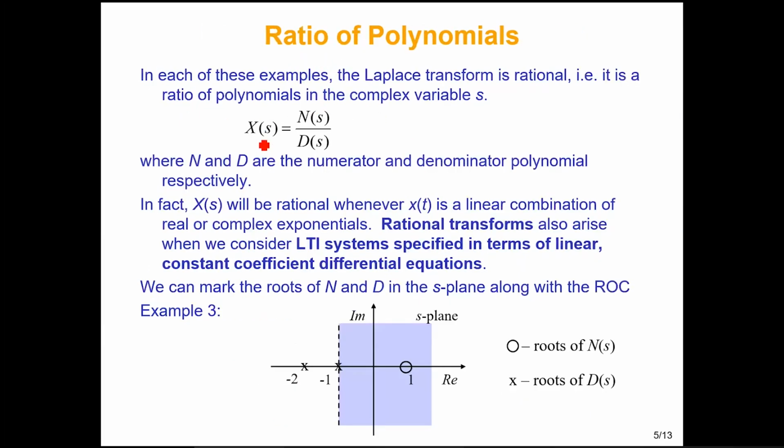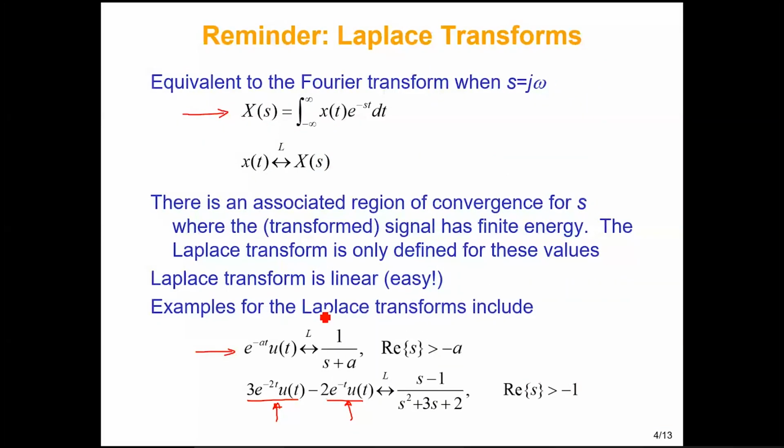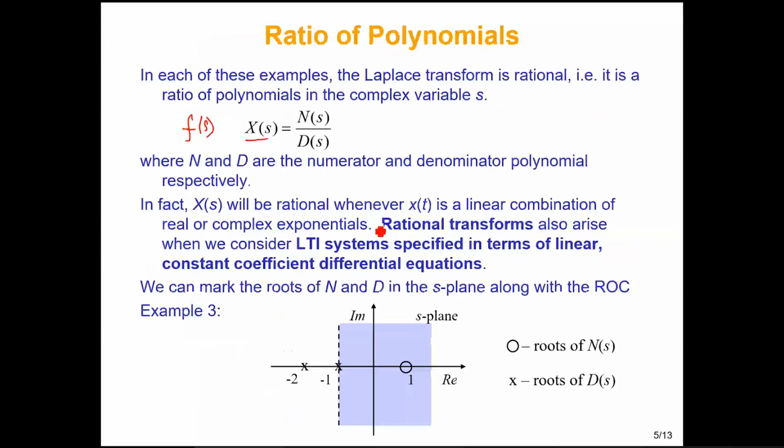Now, once you get the expression of the Laplace transform, it will be some function of s, as you see right here also. You will have some numerator term and some denominator term. The way we find the poles is we put the denominator equal to 0, and the values of s, the roots that we get for the denominator, we call those poles. The numerator and denominator expressions can be expressed as polynomials, or as factor terms also.